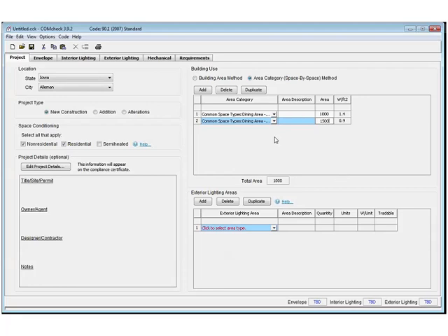The building use types here is really important, especially, well, you can't do your lighting without defining it. But what it gives you before you get into the lighting portion, it gives you those allowed watts per square foot. And each one of these are different. Previously I showed you a screenshot of the different values that you could have, especially if you have multiple space types in there. And then it'll total up your total area square footage. This is also another nice thing to take a look at to confirm that your total area here matches what you have on your building footprint, especially if you have several stories you're dealing with.